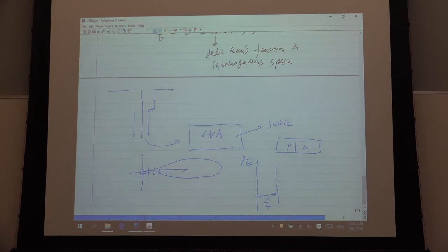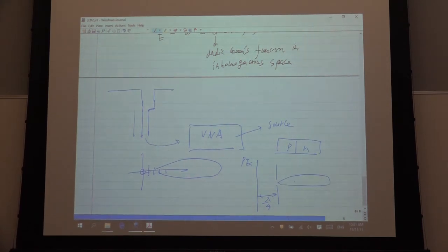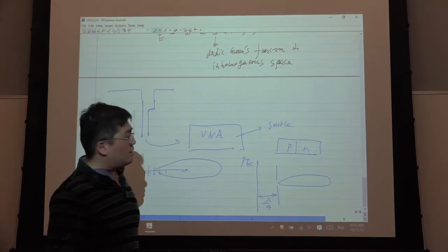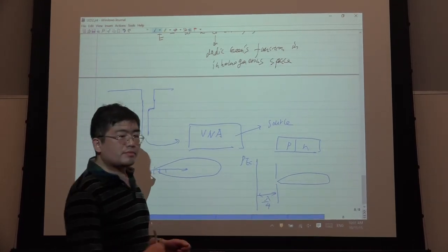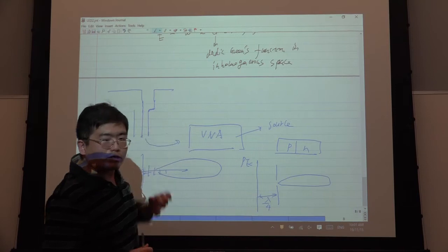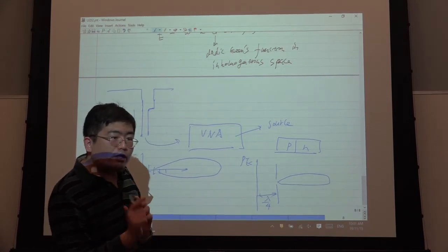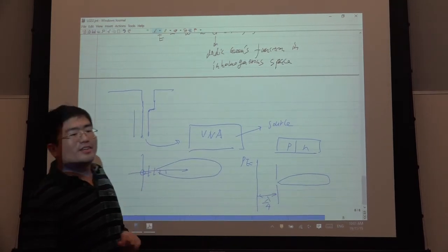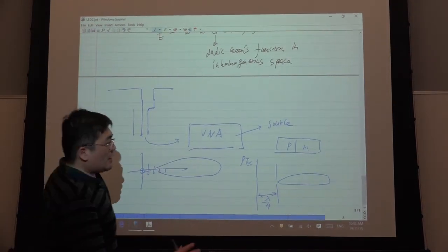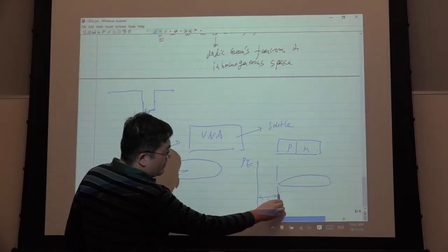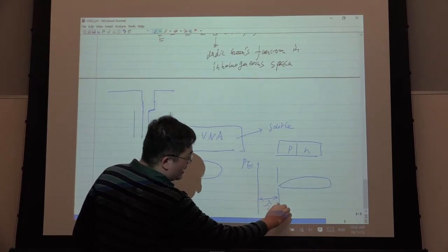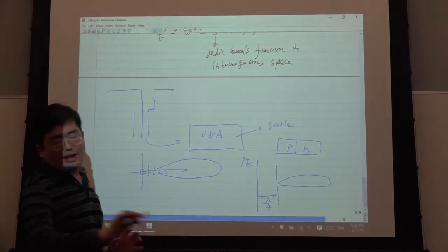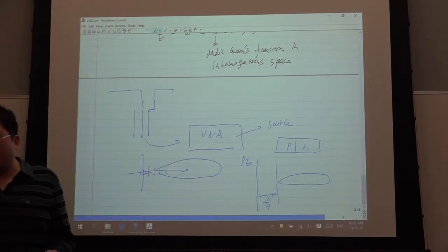I just argue that this is quite different, because at this point it's not a source. But your dipole is a dipole. This dipole is a source. It's an active material. Exactly. This is also called a dipole antenna. So the contribution has induced PEC. From here they go back here, they are enhanced, they double the field at this point. They just change the directivity. They do not change the output power.